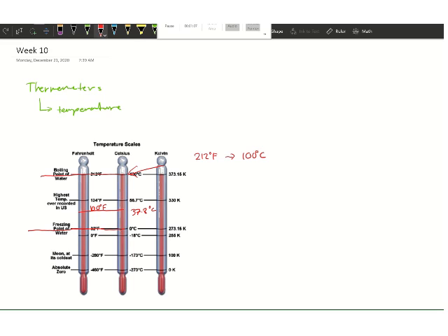It can only measure within a certain range of expansion, and after that the expansion will not be linear, which means it will not correspond to a certain level of expansion, let's say 1 millimeter equivalent to 0.1 degrees Celsius. As it goes beyond and expands further, it will be less linear and no longer consistent. That's why the accuracy is limited to a certain range of temperature only.